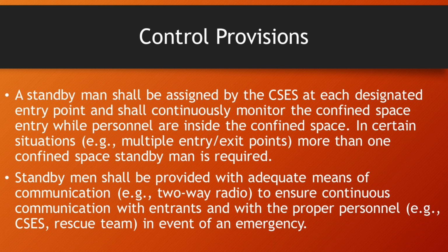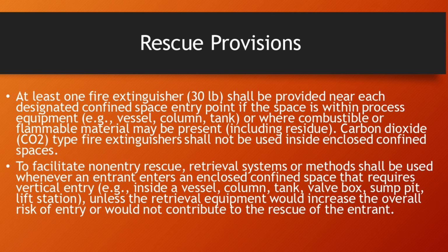In certain situations, for example, multiple entry-exit points or more than one confined space, a standby man is required. Standby men shall be provided with adequate means of communication, for example, two-way radio, to ensure continuous communication with entrants and with the proper personnel, for example, CSCS, rescue team, in the event of an emergency.